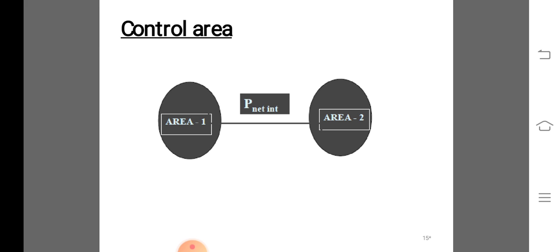Assumptions in analysis. The following points are made in the analysis of the two area system. One, the overall governing characteristics of the operating units in any area can be represented by a linear curve of frequency versus generation. Second, the governors in both areas start acting simultaneously to changes in their respective areas. Third, supplementary control devices act after the initial governor response is over. The following time instants are defined to explain the control sequence.